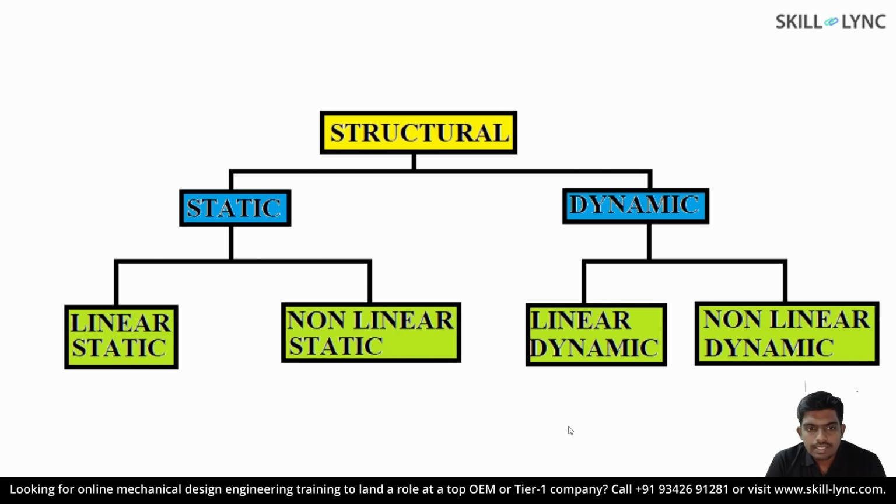Now let's look at the basic classification of analysis, that is static and dynamic analysis. If you consider a static analysis, we assume the forces that act upon the model are quasi-static. In other words, the loads that are acted upon the model increase gradually in such a way that the acceleration and velocity can be neglected.